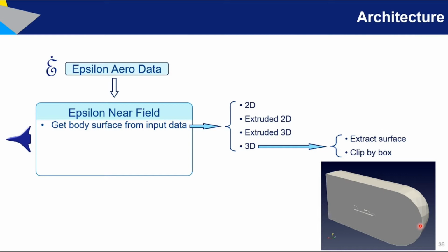That is, we start from the volumetric domain, we ignore the volumetric cells and we retain just the shell that contains the CFD domain. That's basically the external surface. And again, this external surface includes the boundary conditions, the symmetry plane, but also the aircraft body. And that's what we really want to get. In order to separate the body from the rest of the surface, we use the clip by box.